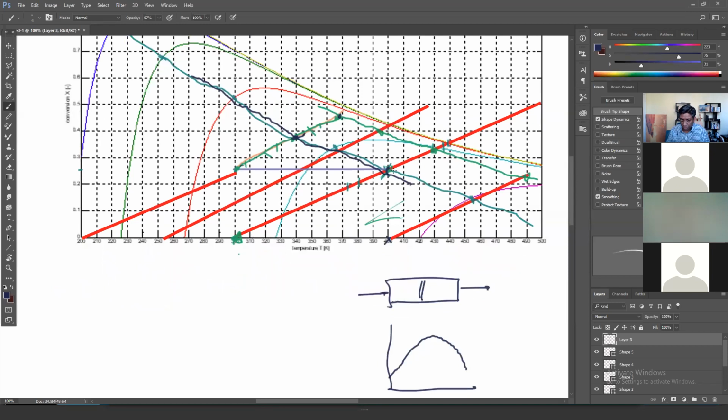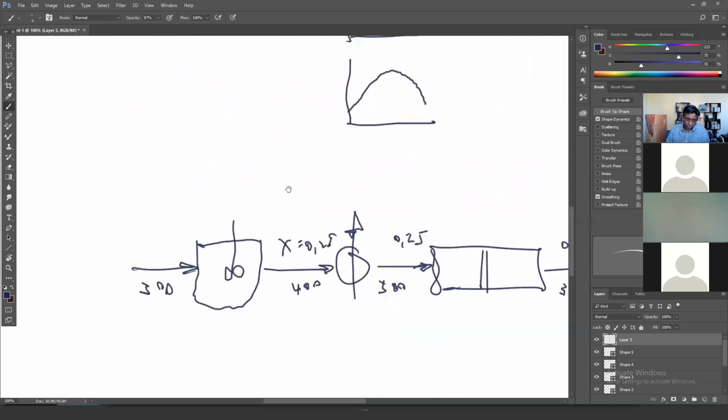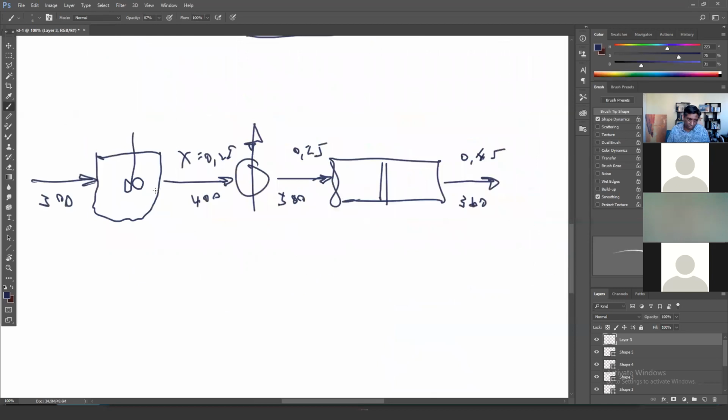If you are going to stop on the maximum rate point for the PFR or the CSTR, you would draw exactly the same line. Same thing here. If you're saying we cool back to 300 and then we straddle the maximum rate line and stop at 10K shy of equilibrium, you will draw exactly the same line. So you would then just draw different symbols in these two positions. It would look the same from that perspective.